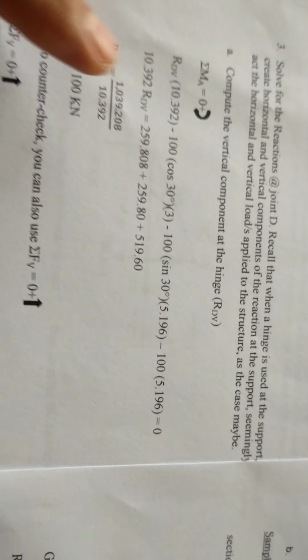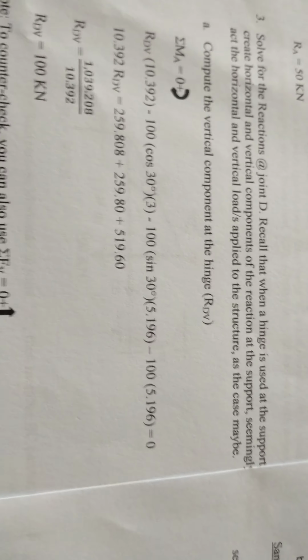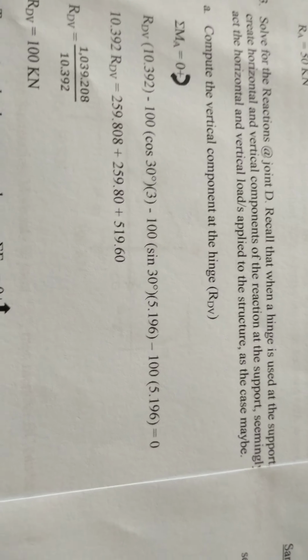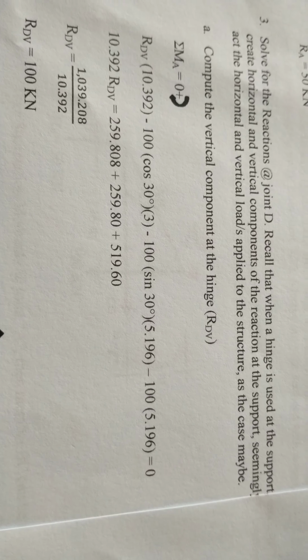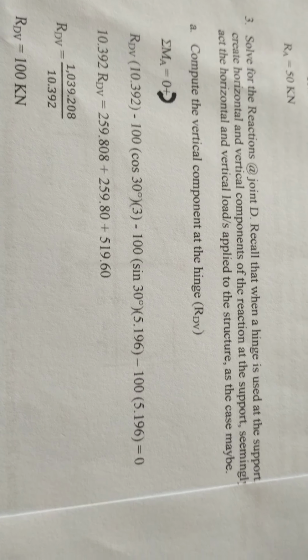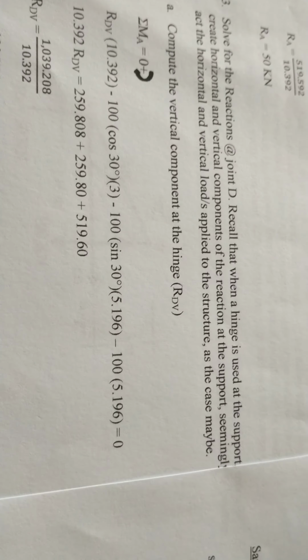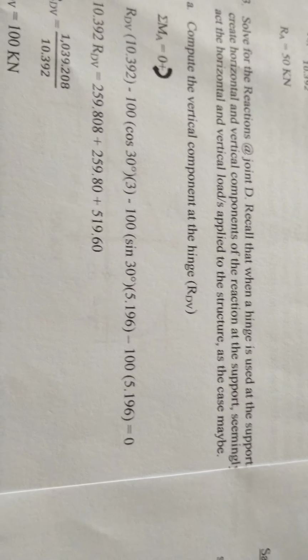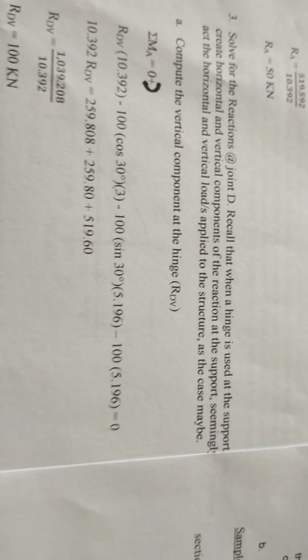So we need to take moments at A. So if you are going, class, to take moments at A, we have RDV, which is unknown, times the moment arm 10.392, minus 100 cosine 30 degrees times 3, which is the moment arm for the